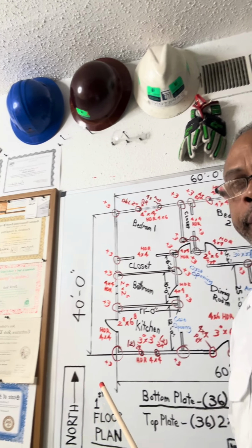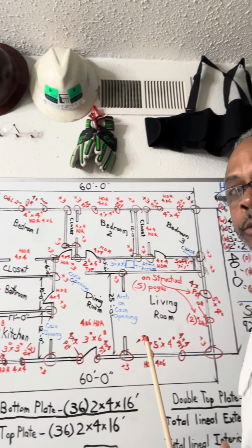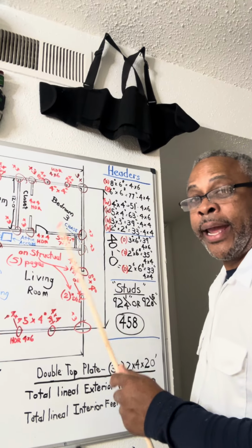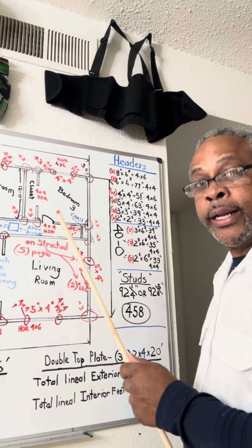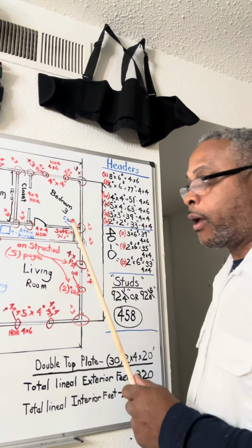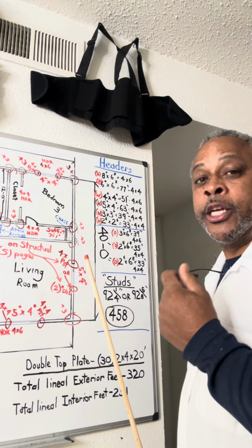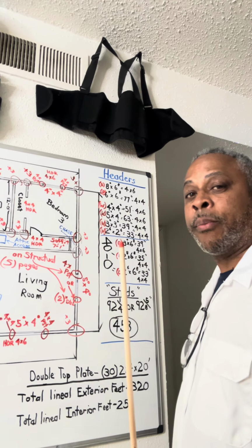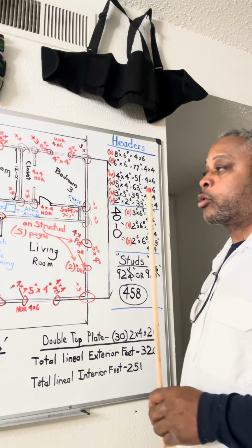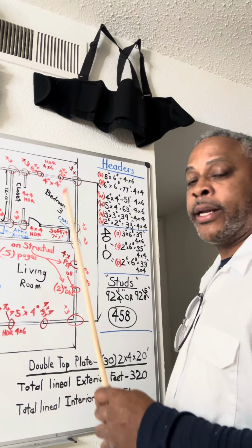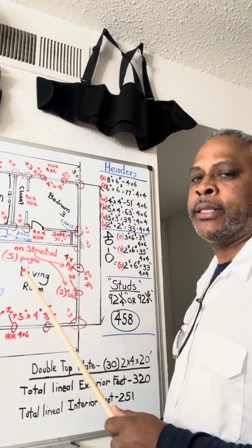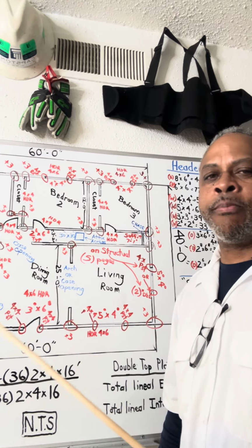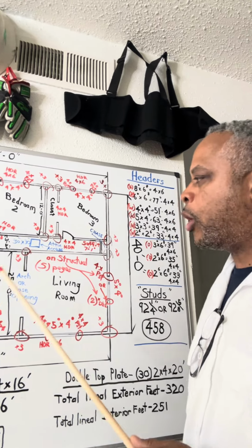Engineering right now is really at its peak with the engineers, and you really need to make sure that you follow the header that is listed on the plans, because if you don't, the inspector from the city, or if you're doing a private job, the representative for the owner, is going to call you on it. That's a lot of cutting out. You don't want to cut out anything on a new construction job. You just don't, because you turned it into a remodel, and that's not professional. You don't want to do that.